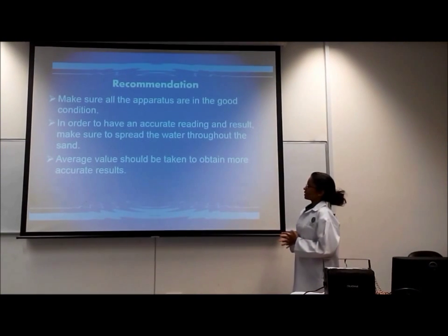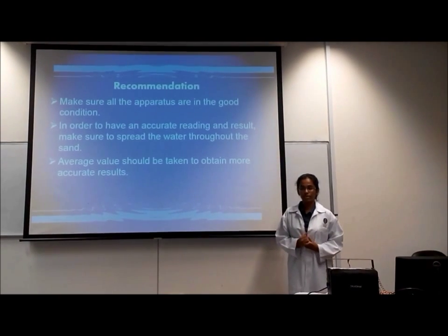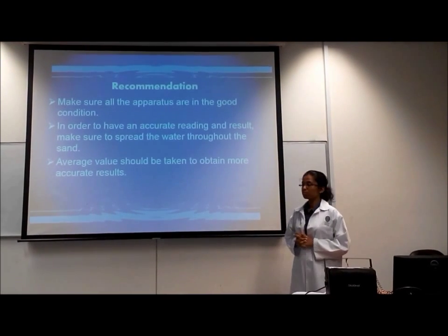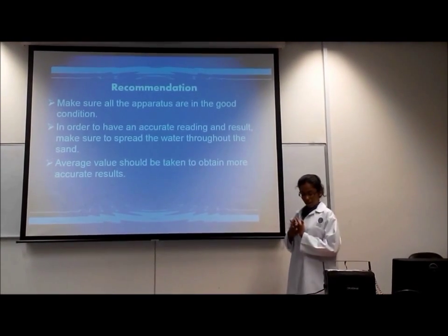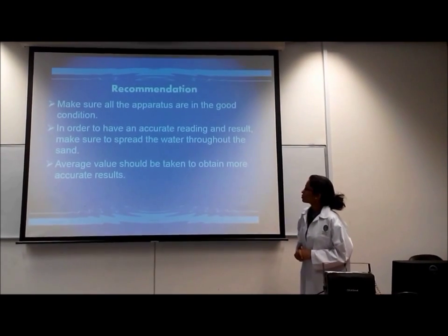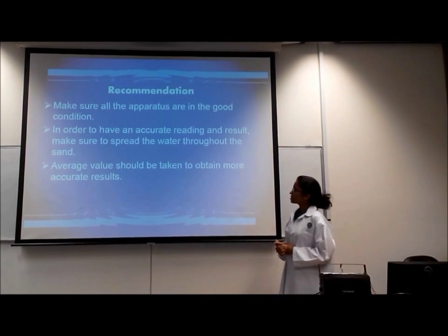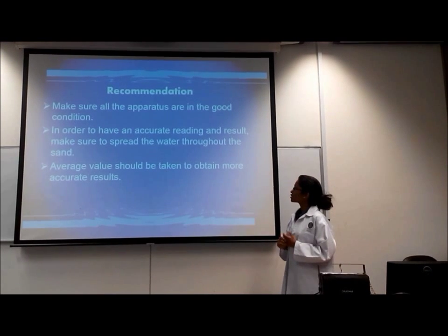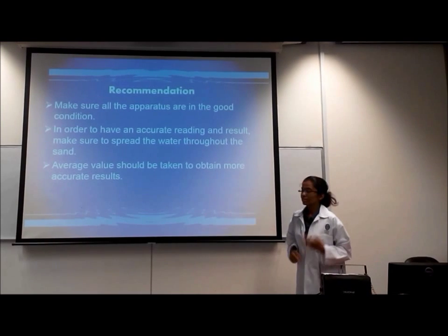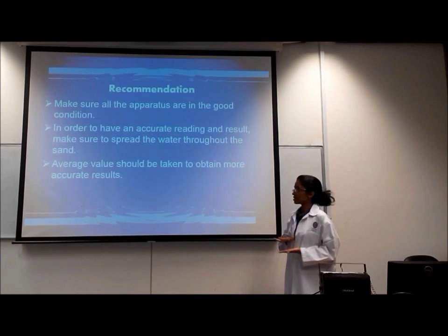Okay, moving on to the recommendations. So first of all, we have to make sure that all the apparatus being used for conducting the experiment is in proper good condition. This is because poor function of the apparatus will affect the final data that's being recorded. And next, in order to have an accurate reading and result, make sure to spread the water throughout the sand, as mentioned earlier. The water has to be sprayed evenly on the tray where the sand is.